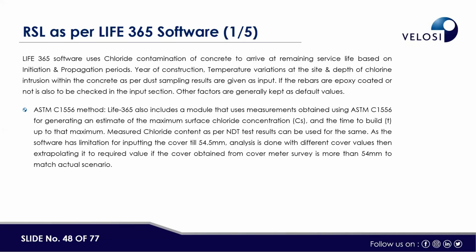So what we have to consider here are the initiation and propagation periods, the year of construction, temperature variations, and depth of chloride intrusion. These are the inputs into the software. If the rebars are epoxy coated, there is a separate drop-down menu in which we can give this input also. The method we generally follow is the ASTM C1556 method.